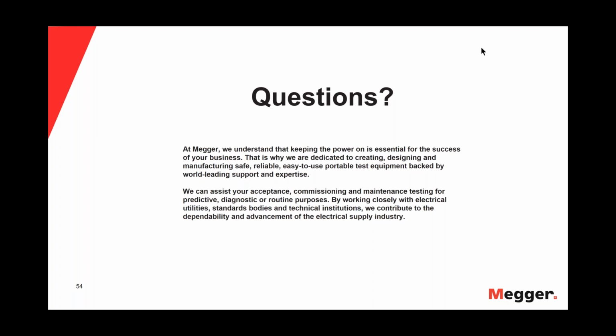So if you have your thumper set appropriately for that fault, in other words, I'm using enough voltage, I'm making the maximum amount of noise in the correct voltage range, then in essence, you're set for the coincidence method. By default, you've got your equipment set in the correct position, if you will.